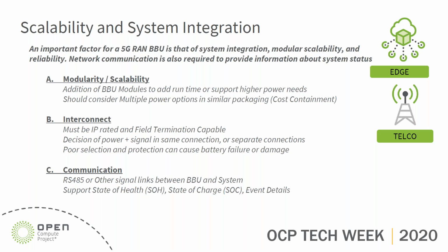So in that, the interconnect has to be common between all of your different modules. So we're talking about the rectifiers, any type of PDUs, and the batteries. Everything in there has to have the same interconnect solution, otherwise you're going to run across some challenges. And because you're running power through them, you have to make sure that all of the connectors and all the cabling are going to be able to support those power loads. Otherwise, you're going to have failures or damage.